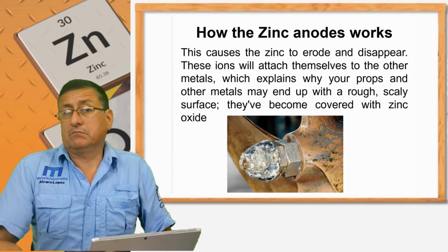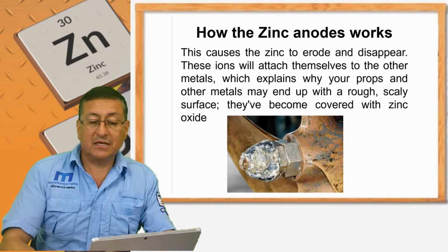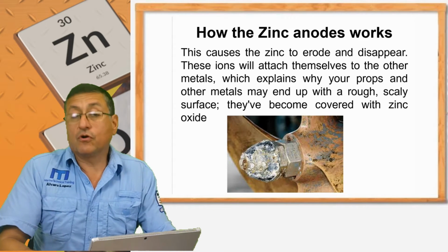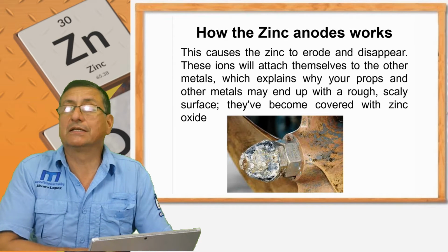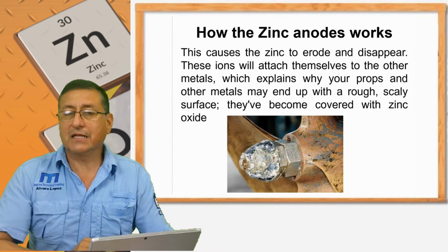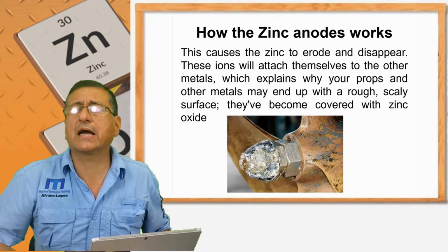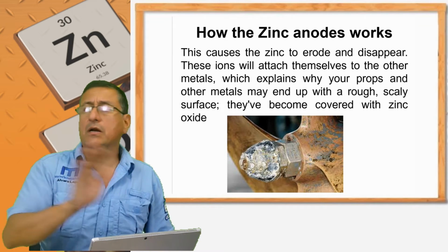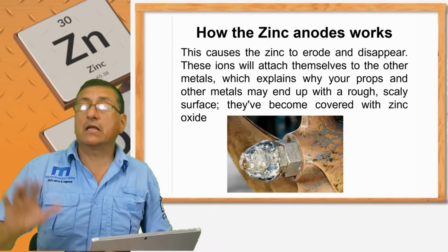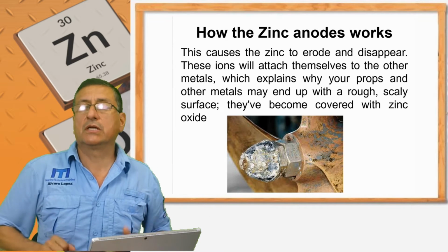For that reason, in general, the zinc anodes are eroded, and at the end of the weeks or days, the zinc disappears because it is completely eroded. And of course, the propeller, the rotor, will be protected. On the surface of the propeller we find a lot of zinc oxide that the flow of water moves and accumulates on the surface of the copper. But the copper is not attacked by that zinc oxide. You can remove that oxide with sandpaper and the propeller will easily be in good condition. This is part of the service: sand the propeller, clean it, remove the zinc oxide accumulated on the surface, and restore the propeller with new paint.